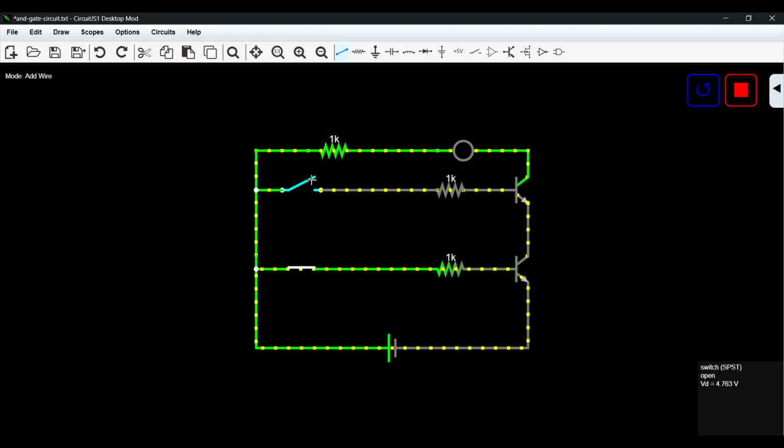And only if we select both of them are the electrons able to flow. The electrical charge is able to flow to the first transistor, since the base is activated, and to the second transistor, since the base is activated. And therefore everything is just like the simple basic circuit that we looked at when we were starting. And that's an AND gate.